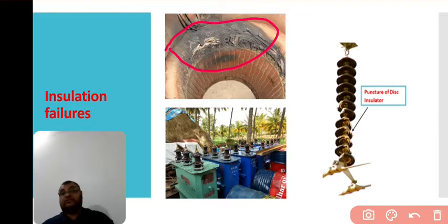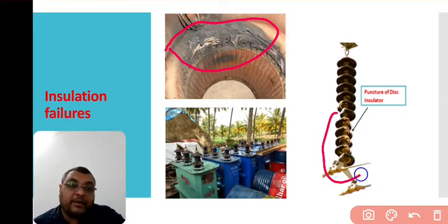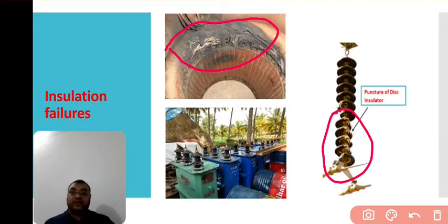A particular part of that winding is going to be damaged. Okay, so electrical equipment is always subjected to internally generated or external voltage and current surges, because the main reason for the failure of an electrical component is internally generated voltage or higher current due to surges. A physical rupture of insulation with the destruction of molecular bonds might occur during a voltage surge. You can see the physical damage here, the complete puncture of the disc insulator.